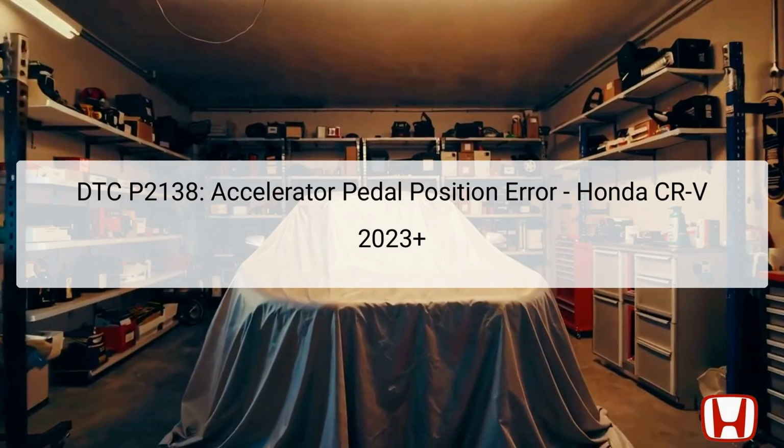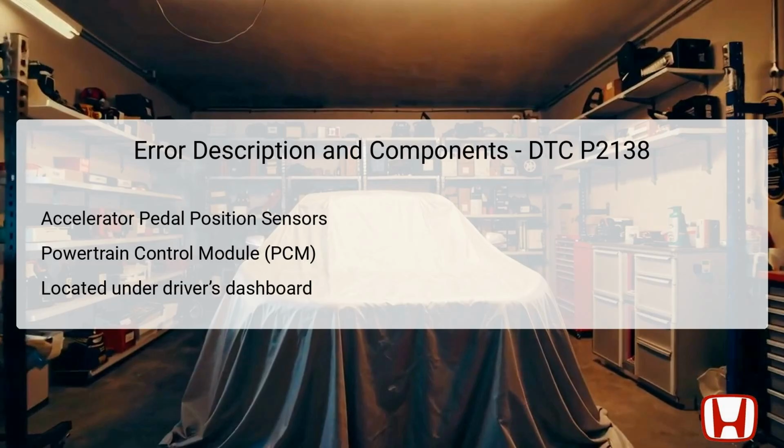The APP sensor is integrated within the accelerator pedal module, typically located beneath the driver's side dashboard. This code reflects the PCM's detected voltage deviation, suggesting there is a malfunction that needs immediate attention to ensure vehicle performance and safety. The DTC P2138 is related to the functionality of the accelerator pedal position sensors A and B, which measure the pedal's position to relay accurate information to the vehicle's powertrain control module, or PCM.